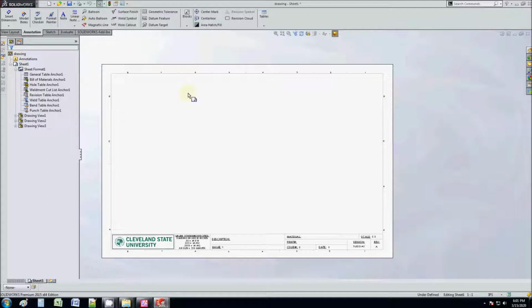An alternate way of doing this is to create a packet of individual drawings. So what you do is on the engine block, you put a bunch of references, a bunch of notes to say, hey, reference drawing A, B, C. And all these drawings become a bundle. They become a bunch of references that can fit inside an 8.5 by 11 booklet. And that's another clean way to communicate a complex object like an engine block.